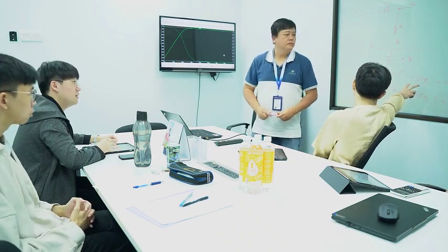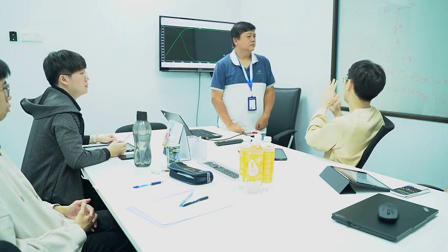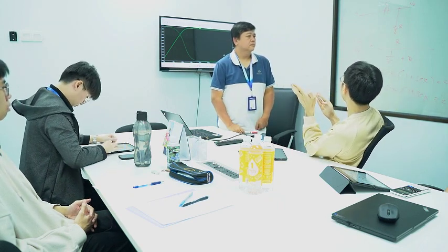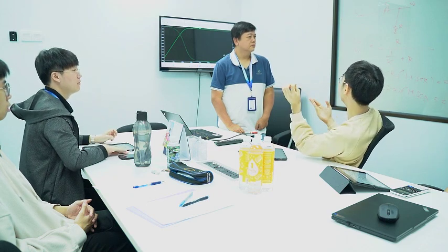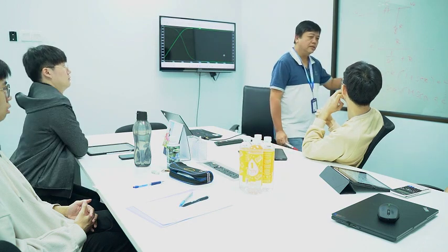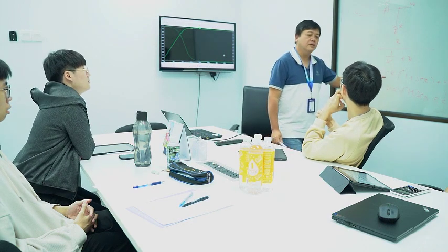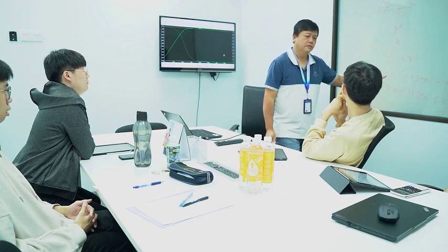Because if there is a pole, the gain of this one contributes to the phase which starts 1 decade earlier. But if this is starting from 0, then there is no 1 decade earlier, so you cannot see the effect. This one always starts very early, even before the second pole comes in.